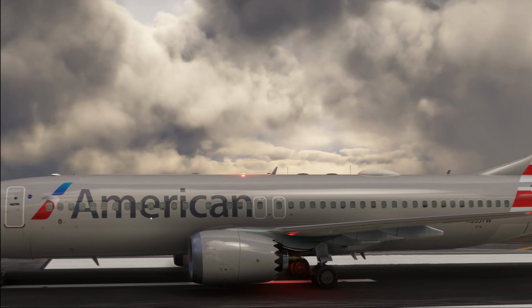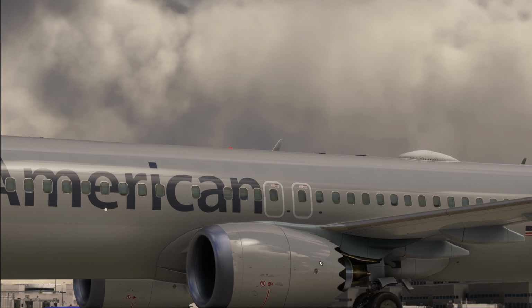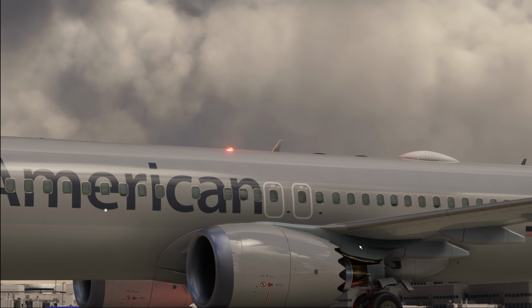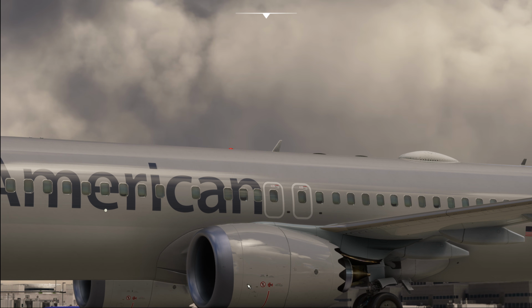You've got that huge engine over here, and when you shut the engine down, obviously the warm air is going to rise to the top, and you will have cooler air at the bottom. This will mean that the fan blades that are located towards the top, the same goes for the turbine blades and the compressor blades, by the way, will be warmer and therefore show different characteristics than the ones that are cooler at the bottom.